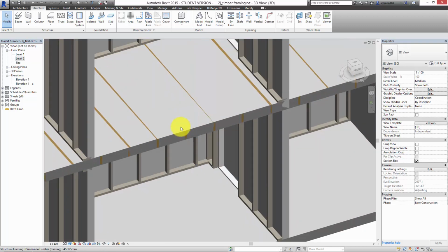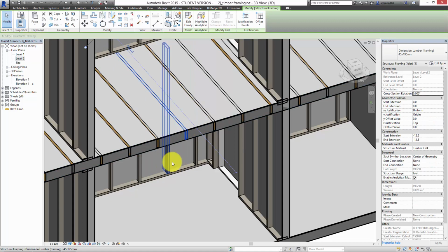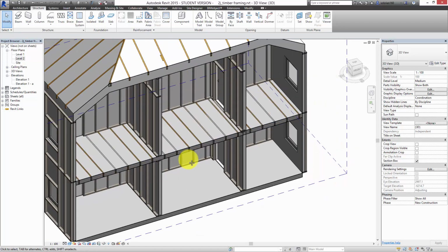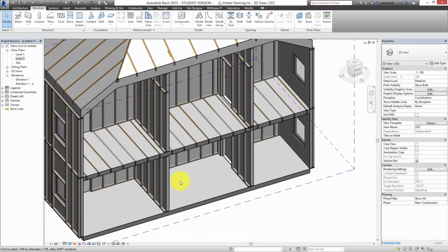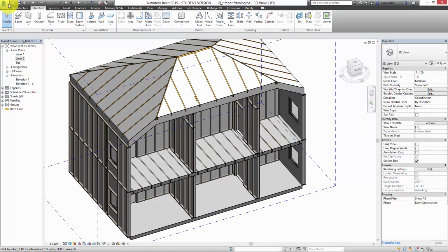Let's say we wanted to make a specially shaped beam for this element here, if we're making it out of concrete or something. Whenever you're making something special in Revit, it's always a family. So we did annotation families in the intro period, which allows us to do repeating details and so on, just in 2D. But in 3D, we can actually make architectural objects.